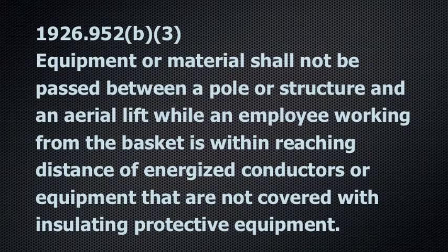Section B3. Equipment or material shall not be passed between a pole or structure and an aerial lift while an employee working from the basket is within reaching distance of energized conductors or equipment that are not covered with insulating protective equipment.